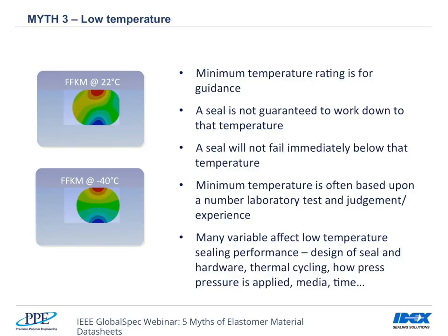In a similar way that the CTE will increase the volume of material as temperature increases, when temperature decreases, the material will contract, reducing the volume. This has a knock-on effect in terms of its design and performance by the sheer fact that the squeeze is reduced.